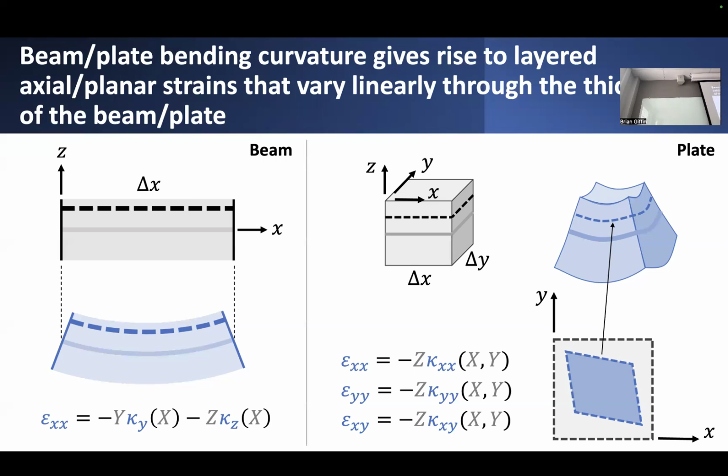And it turns out that there's a direct correspondence between each of those different mixed terms of curvature, represented as different partial derivatives of the transverse deflection with respect to x, y, or x and y. And I notice that really these different components of in-plane strain just vary each linearly with respect to depth z. Kind of cool.